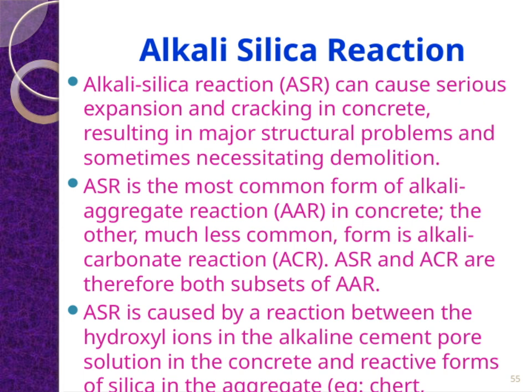Now, what causes ASR? It happens when the hydroxyl ions in the alkaline pore solution of the cement react with reactive forms of silica present in the aggregate. These silica sources can include materials like chert, quartzite, opal, or strained quartz crystals. The reaction produces a gel that expands over time, leading to those damaging cracks we're trying to prevent. Understanding this reaction is key, because it highlights the importance of selecting appropriate aggregates and controlling the alkalinity in our concrete mixes to avoid these issues altogether.